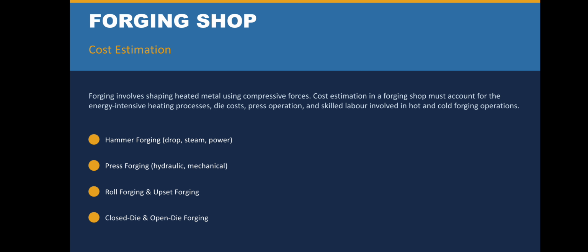Setting down process is an operation which usually follows drawing down. This operation can be performed with a hammer and a flatter. This is the main difference between the drawing down and setting down process. This method is mostly used for the smoothing of a square or rectangle article.